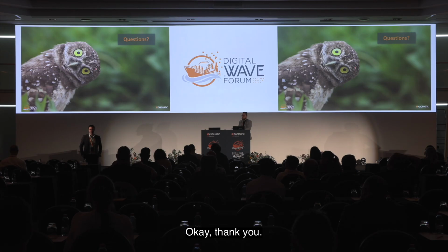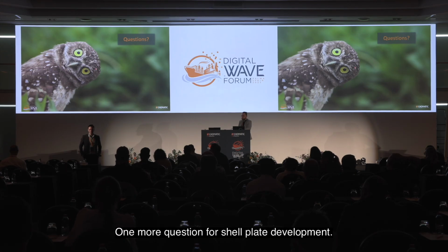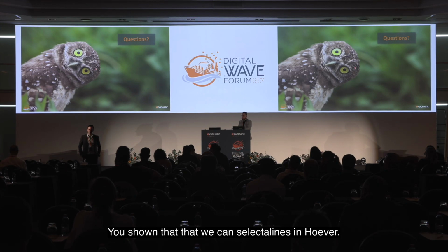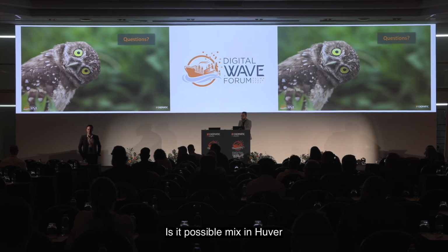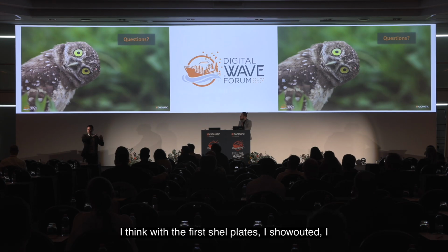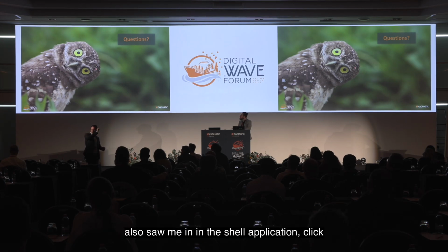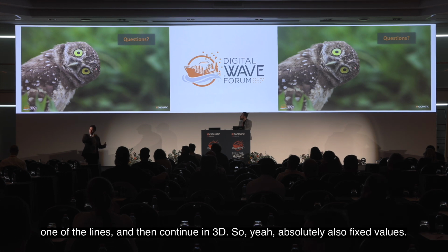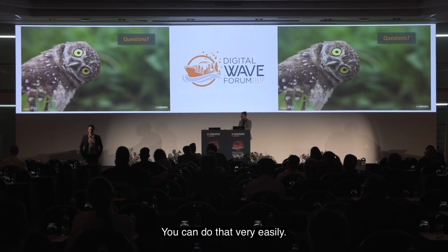Okay, thank you. One more question for shell plate development. You showed that we can select hull lines in Hull Viewer. Is it possible to mix hull lines in Hull Viewer and coordinates in Hull? Yeah. You can mix and match, and I think with the first shell plate I showed, I also saw me in 3D in the shell application, click one of the lines, and then continue in 3D. So yeah, absolutely. Also fixed values, you can do that very easily. Thank you.